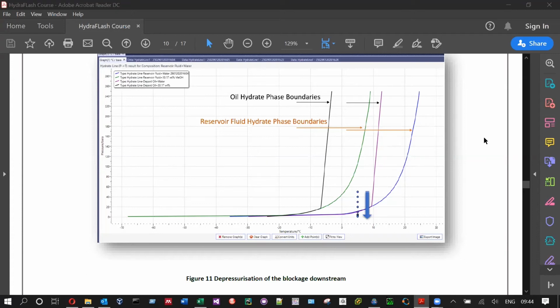For example, if the methanol concentration required for this inhibition is 20%, they normally consider 3 degrees of safety margin, some countries 5.